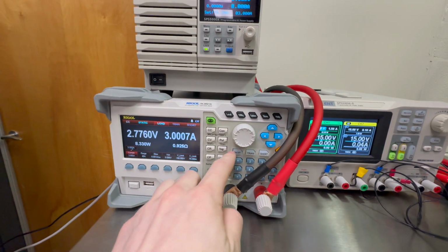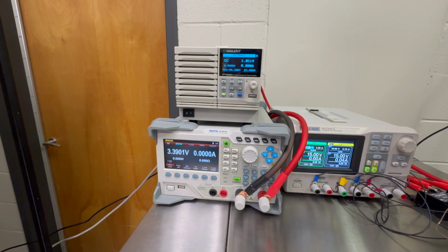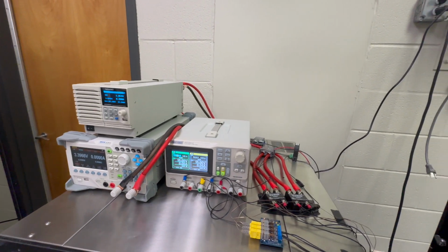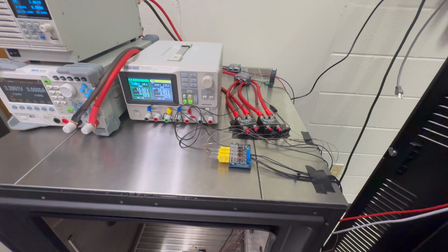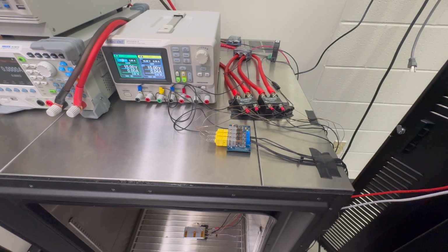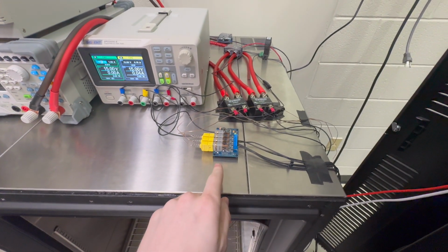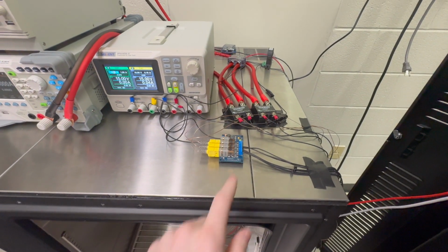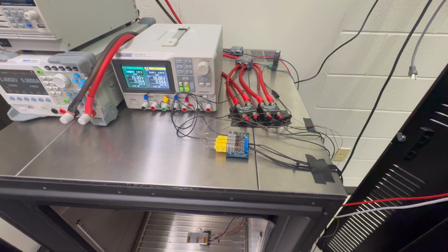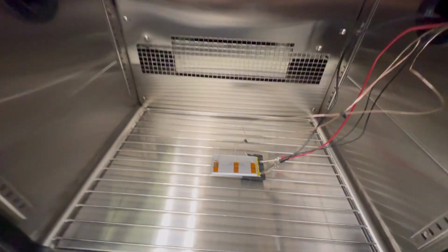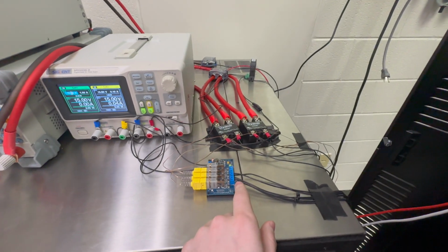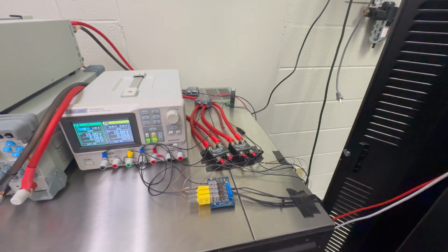You can go ahead and turn off there. We have a power supply, which is powering our current sensor and our thermocouple amplifier. The thermocouple amplifier, which we see is right here, supports up to 4 channels, but we're utilizing 3 channels, and we have 3 K-type thermocouples, which sit on the battery and monitor the temperatures, which are then reported out of their analog ports back to Opal RT.